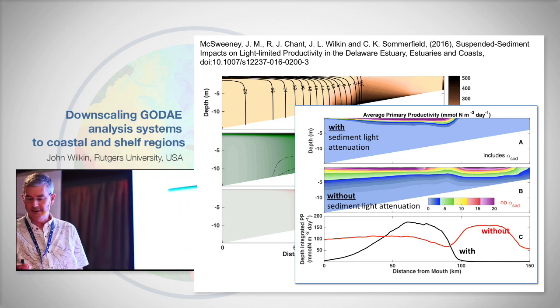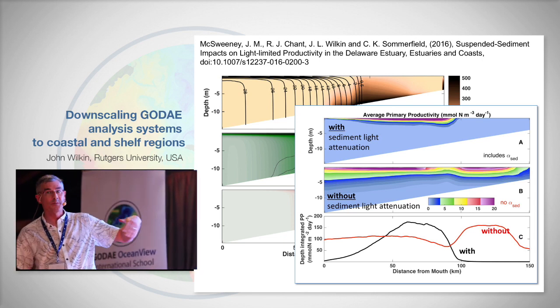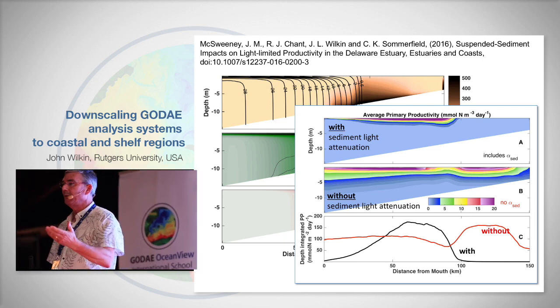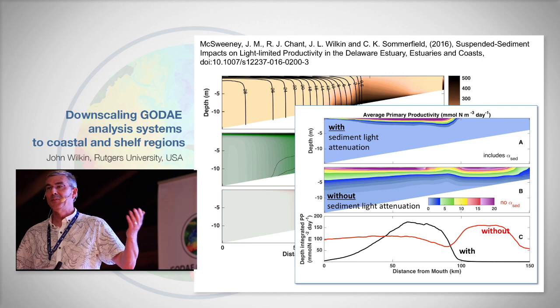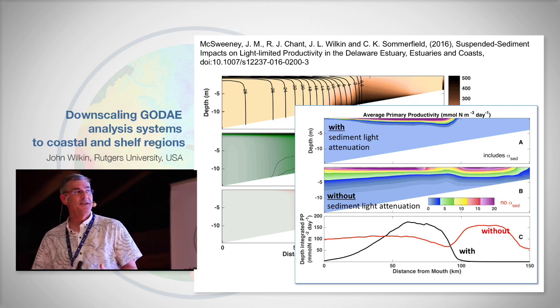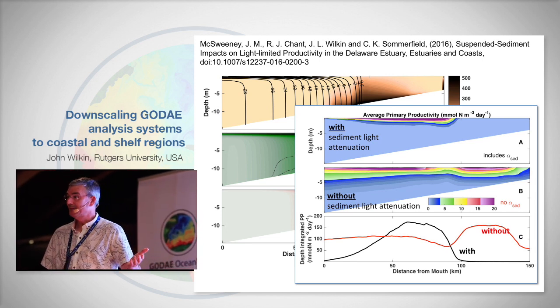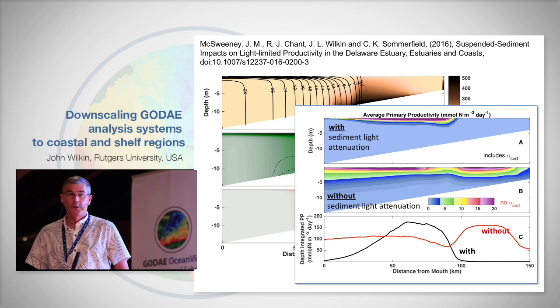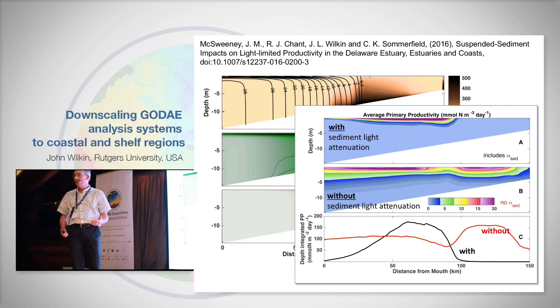So these are important factors if you're trying to carry through to water quality in an estuarine environment. This would be actionable guidance for someone that's trying to decide, should we put a lot of effort into reducing the nitrate load in the Delaware River? You could say, well, maybe not, because there isn't enough light to ever give you a nuisance algal bloom. Whereas in the Chesapeake Bay, it's absolutely a problem.